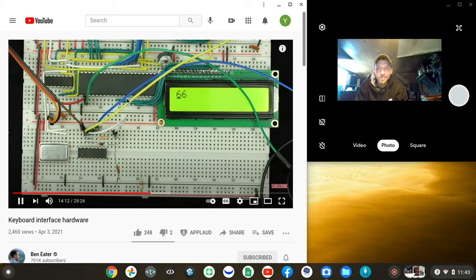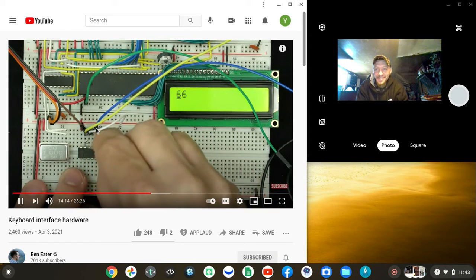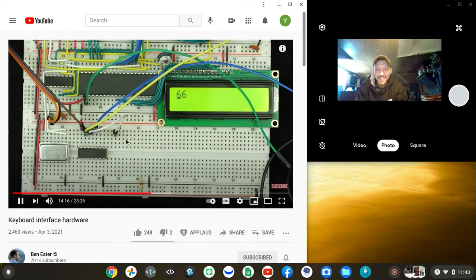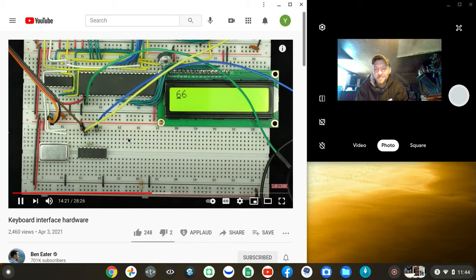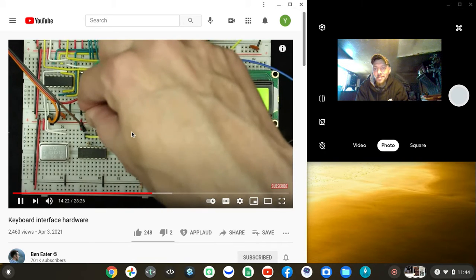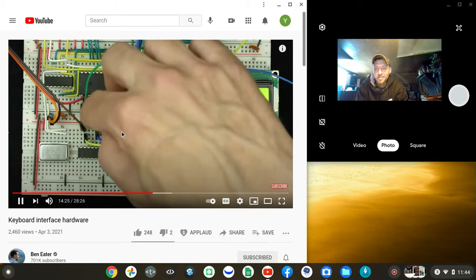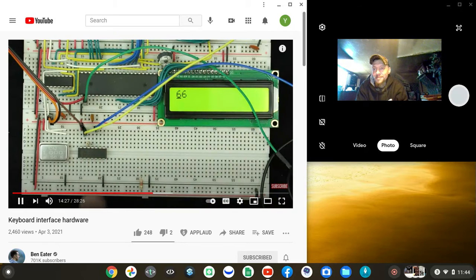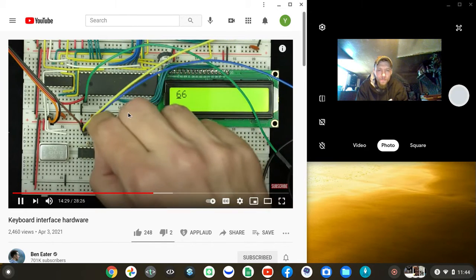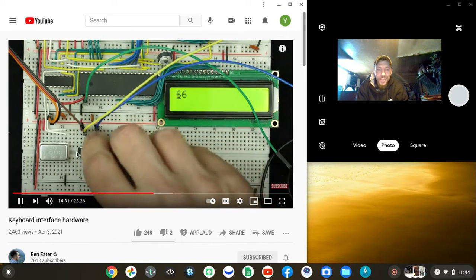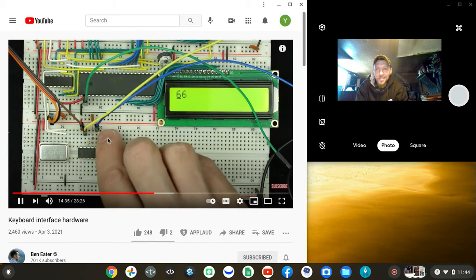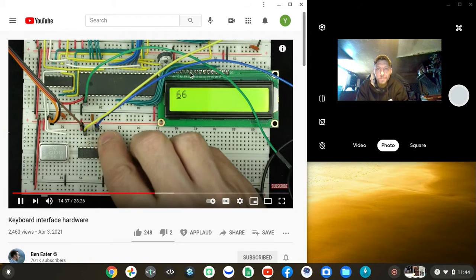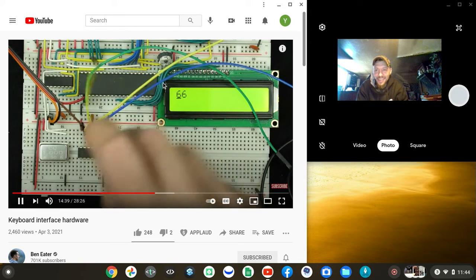So let me go ahead and tidy this circuit up a little bit now that we think we've got something that's working. I'm not changing anything here. This is the same 33K resistor, the same 0.01 microfarad capacitor going to ground there, and then the same diode going across. Then the same resistor there, and here's the inverter. The output of that inverter is this signal, which triggers the scan code. So I'm going to connect that to the interrupt input.